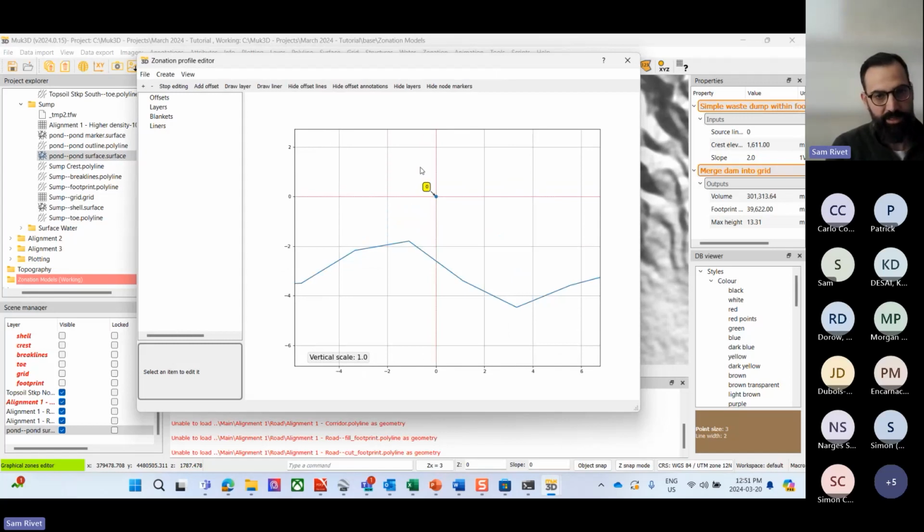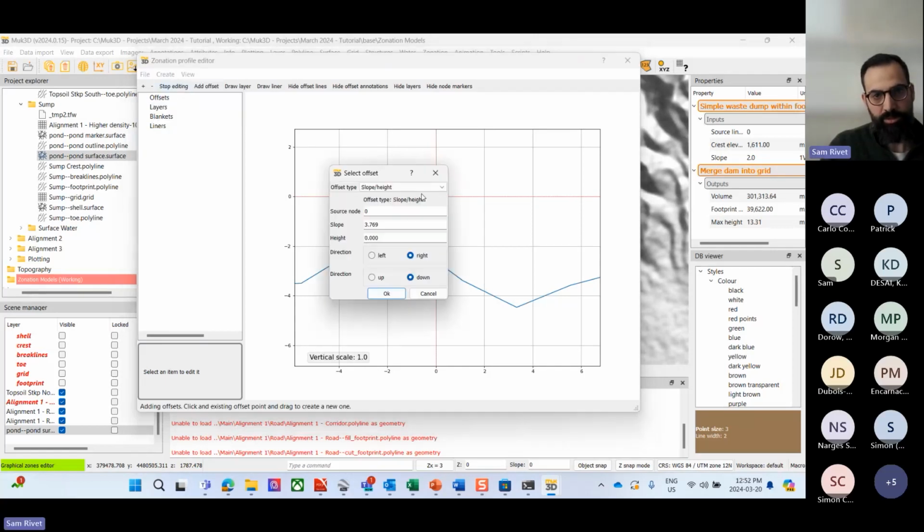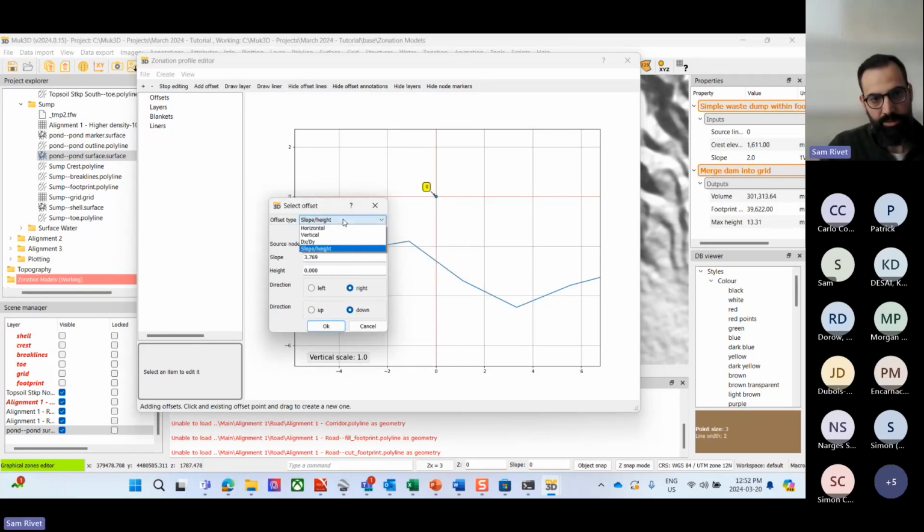It's designed largely like offsetting lines, except you're offsetting points. So you can see here, you're starting at node 1, and then you can start adding nodes. I'm going to click on node 0, and it's asking me, how do you want to offset it? I like dx, dy, simplest, just difference in distance in x, difference in distance in y. Okay, so I want to build that crown. Now these are not exact measurements, but I know I'm going out at 8.5 meters, and I'm going down 0.17 meters. And I think that roughly reproduces like 2%.